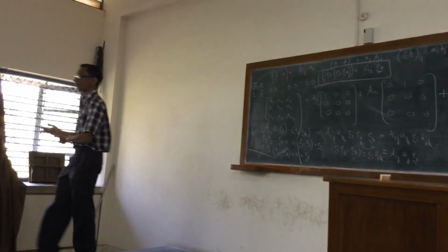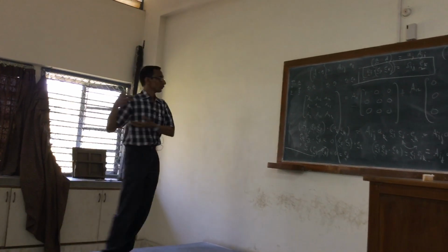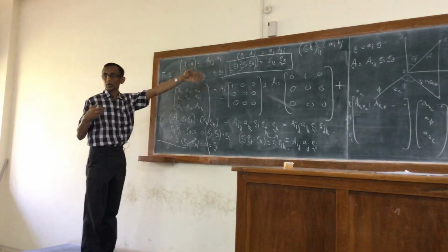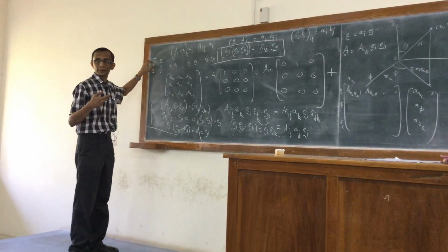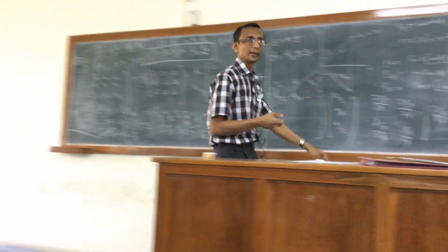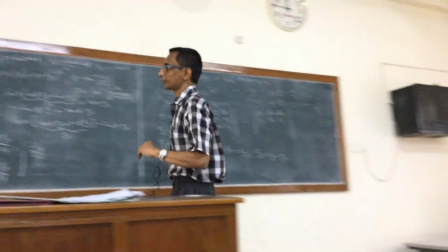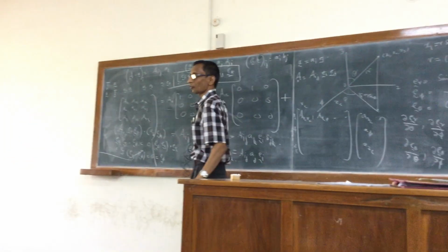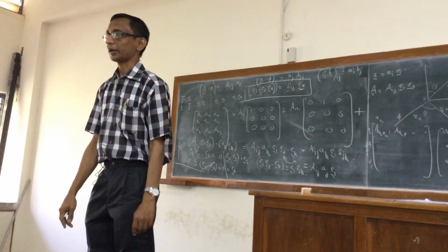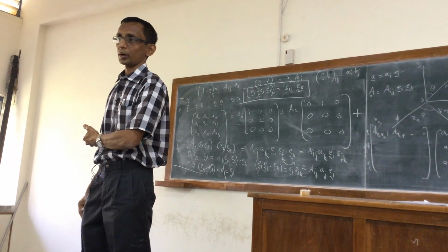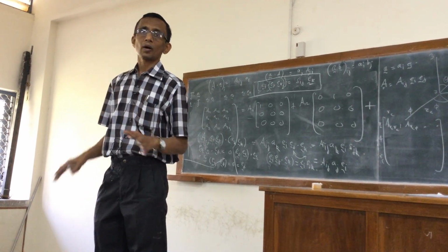Right? Now I can do the same thing in the cylindrical coordinate, whichever I want. Express the normal in terms of its cylindrical coordinate components, and the tensor in terms of cylindrical components, simply multiply one by the other, you will get the vector in the cylindrical coordinate system. And this is possible because these operations involving the dot product of a vector with a unit tensor or a unit tensor with a unit vector carry over to the cylindrical coordinates. Are there any questions? So these are not the complicated issues.